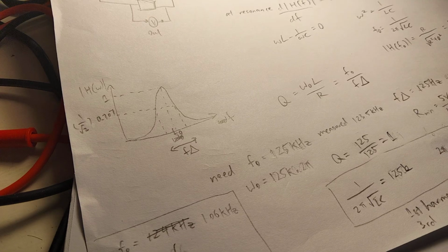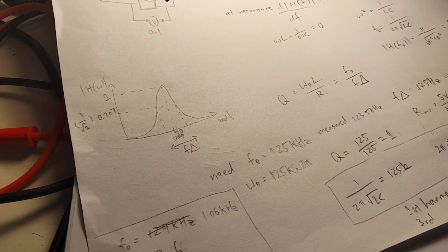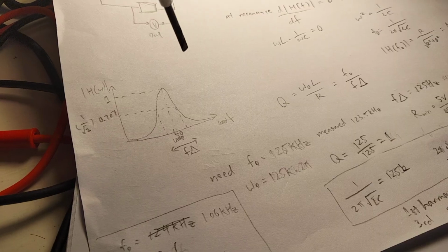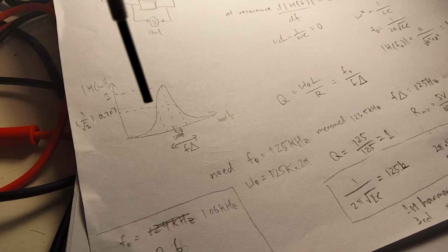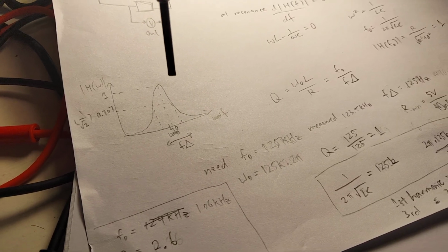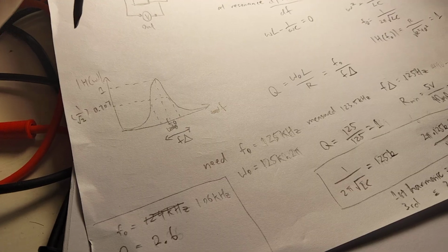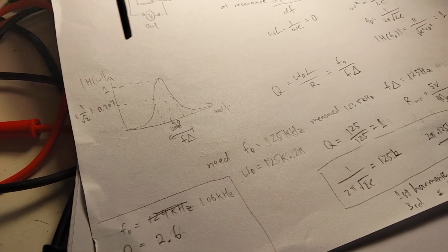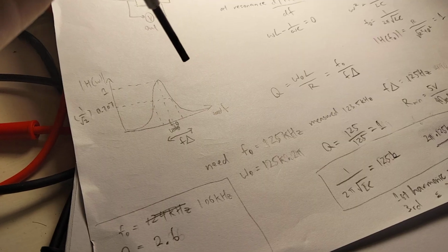So the fundamental frequency is the frequency of the square wave, and then every odd harmonic after that, when added together, becomes the square wave. It's quite intuitive actually, because you can't have other frequencies that are not harmonics of the fundamental. Otherwise, it will not be a regularly occurring square wave if you sum everything up.